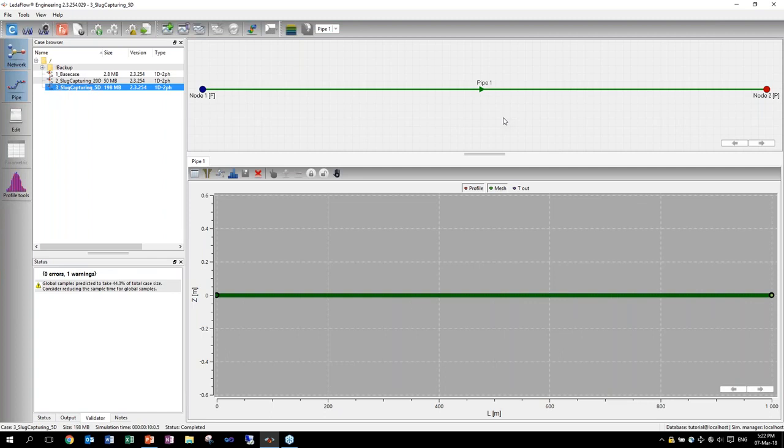That is to be expected for hydrodynamic slug flow, because this is just a simple straight pipe. But the slug length is not really related to that. The slug length can be much shorter and still have the same velocity, or longer.